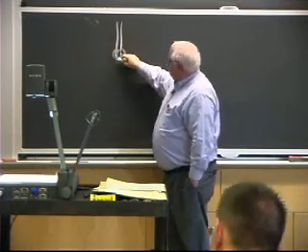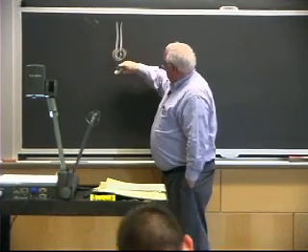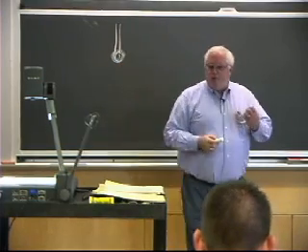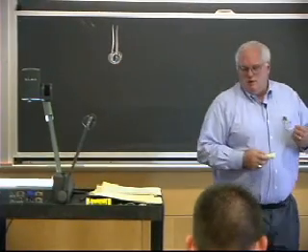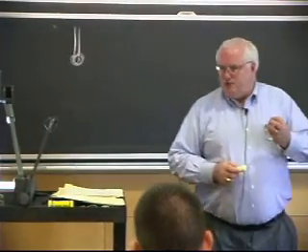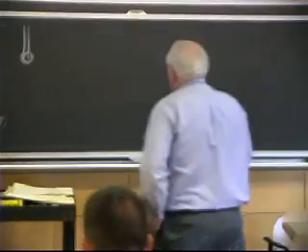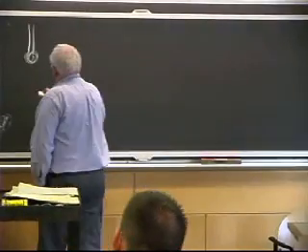So this might be a 1/16 of an inch in diameter, which is 1.5 millimeters or so. And remember, surface tension is going to form a ball, and it's going to be fairly spherical for anything less than about 3 millimeters in diameter. So you get a little ball on the tip, and that tends to be hot.